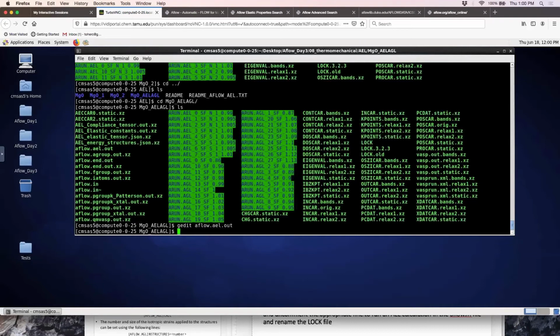This is a bit more involved. The advantage of the second method is that not every DFT code will calculate the stress tensor. But if you have access to the stress tensor, you have access to a lot more information than just the energy. So you can reduce the number of calculations you have to do. VASP gives us the stress tensor, so it makes sense to use that information.